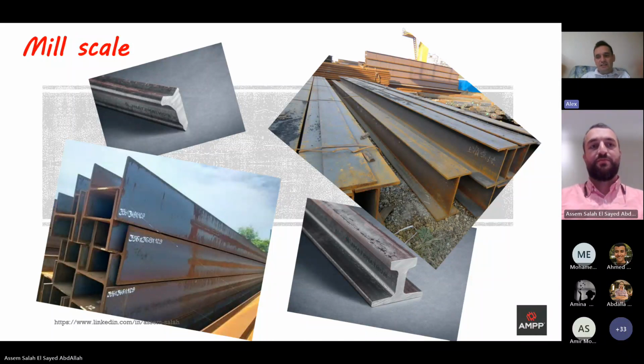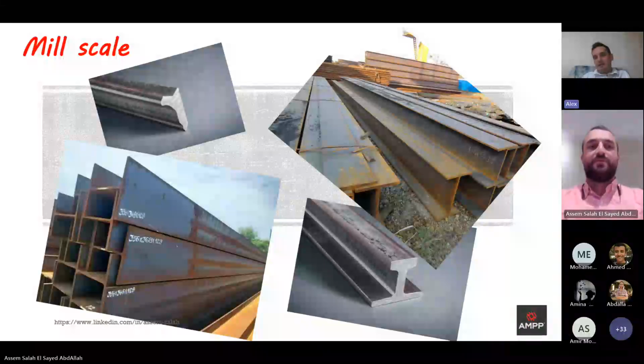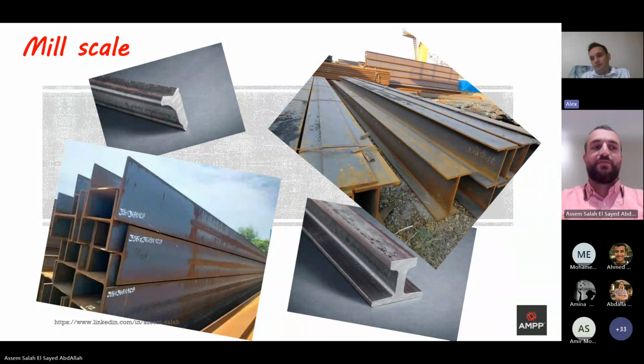I mean, sometimes it takes 6 months. It depends on the region, as we said, because at the sea coast it will take less time. Somewhere in the deep dry regions, it would take much more time to wait, because you can just leave the steel outside and wait until the mill scale just falls down by itself. A passive way of surface preparation. It's a very good expression. Yes, no money consuming. It's only time consuming, if you have time, but not money consuming.